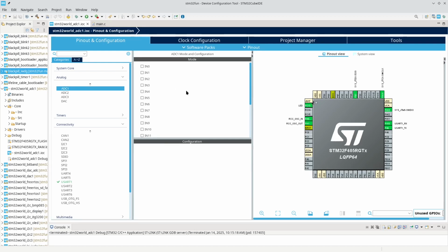Now, the interesting part is we will do this video without hooking anything up. We'll just run it on the MCU itself, because if we look down here, it actually has 3 internal channels. They are wired up internally in the CPU, so you can measure the temperature of the CPU itself. That is not necessarily the room temperature. It will probably be quite a bit warmer. That is to be expected.